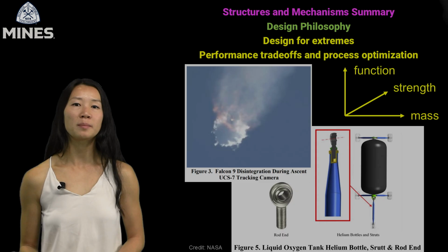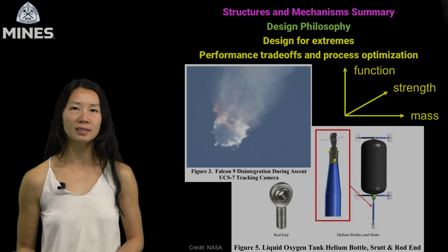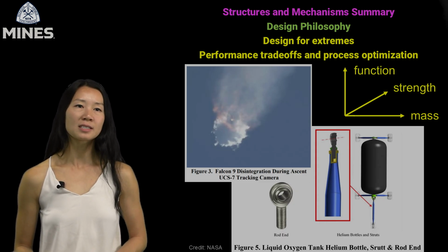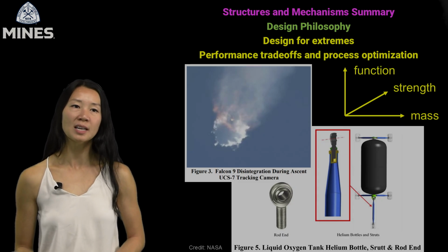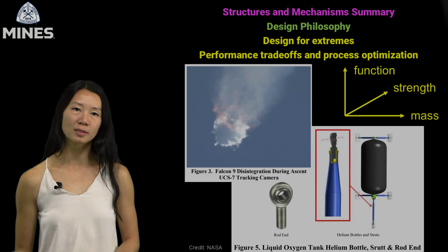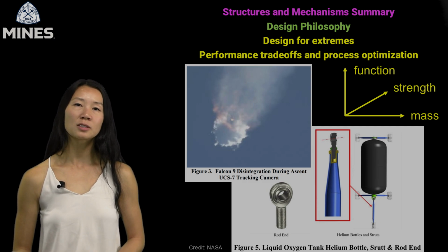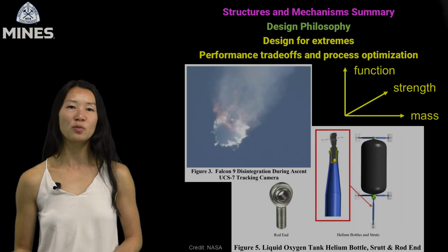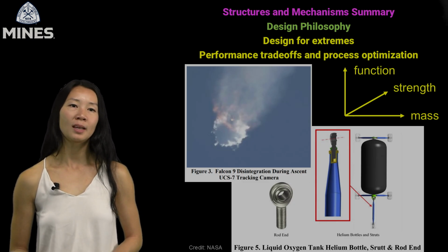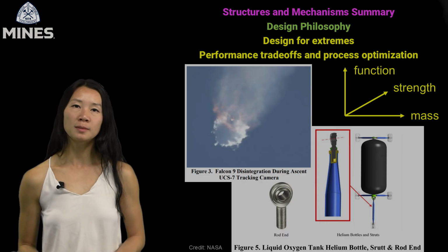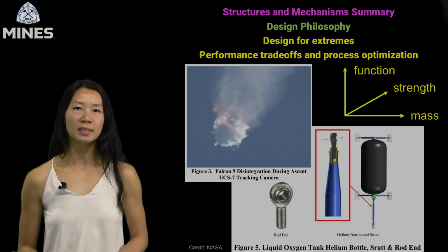If it failed without being noticed, it could lead to catastrophic collapse. So engineers designed a fail-safe jack screw with a secondary follower nut that would automatically take over if the primary one failed. It included mechanical and electronic wear indicators so technicians could spot the problem before it became mission-ending. This type of redundant, inspectable design is key to structural integrity.